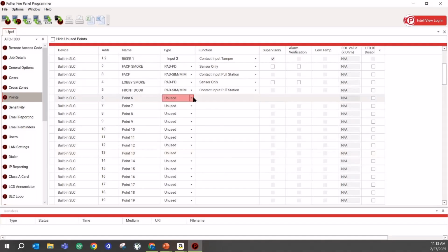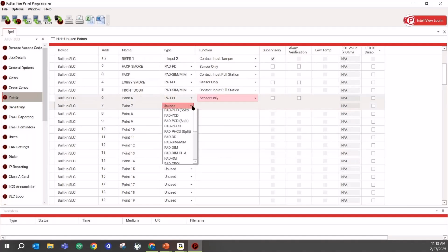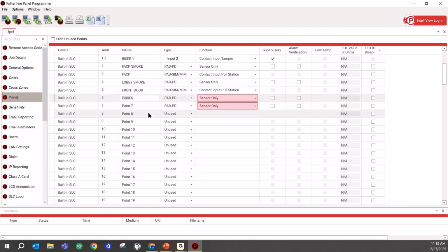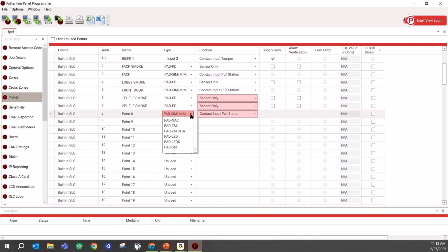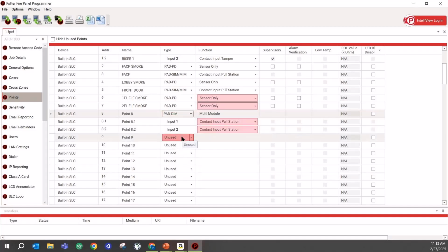So first things I'm going to add are going to be a couple of smoke detectors. Now, I realize we're building out a 2-story building, so elevator recall is a little ridiculous here, but let's go ahead and make believe that the building's larger. So there's my first and second floor elevator lobby smokes. I'm going to go ahead and say that the elevator, shaft, and mechanical room are sprinkled as well. So because of that, this allows me to talk a little bit about a new code thing.